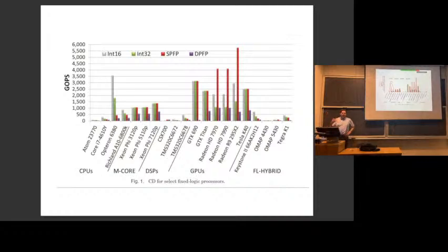So it's the SIMD width gets wider. If you look at the list of SIMD operations for this AMD processor, it's pretty much the same for other processors. They basically make a certain width of data path for SIMD instructions, and then if you use narrower operands, you get more operations. I can't remember the details of this exact processor, but let's say it would probably do 4 32-bit operations in SIMD instructions, or 8 16-bit.